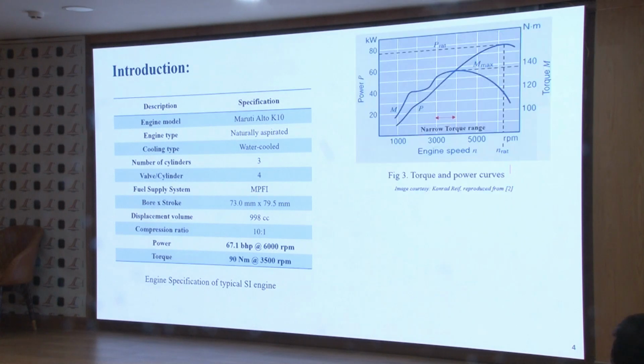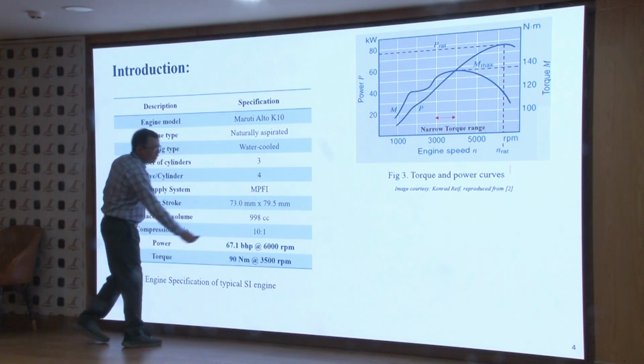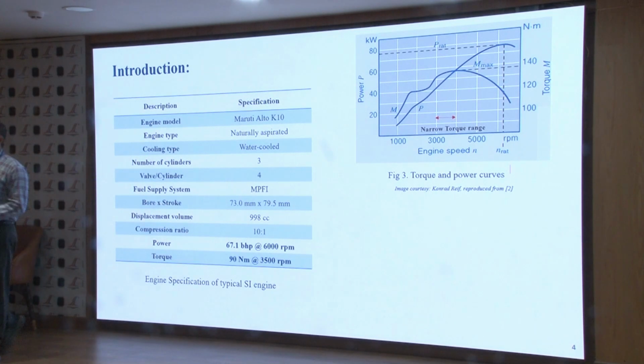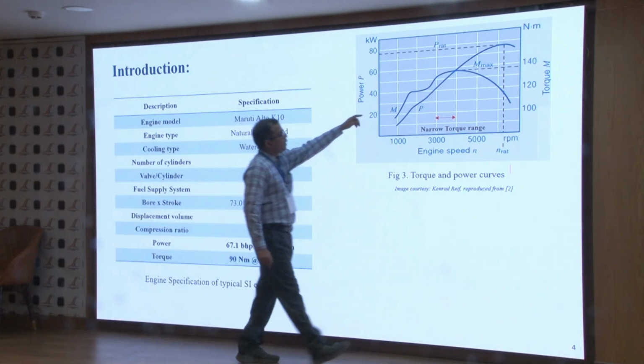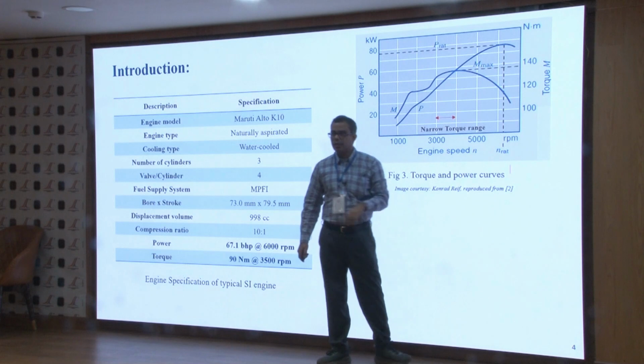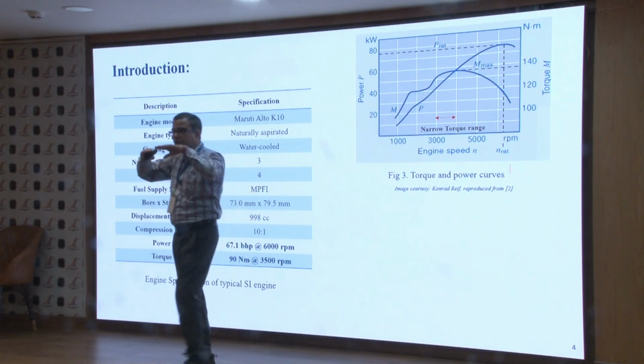The second thing that comes to mind is that whenever we see the power or torque output of the engine, you find that this is the power output at a particular engine speed, or in a very short range of speeds. Why is the power or torque output coming in such a short range? For example, the maximum torque output can be a flattened curve.